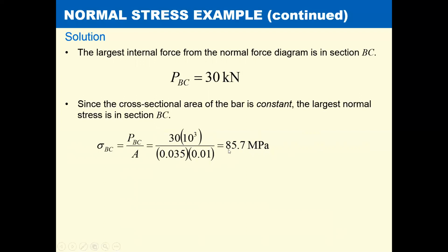And so we don't want to write out an answer with a whole lot more significant digits. In fact, maybe even 3 significant digits here might be stretching it a little bit. Maybe it's a little more appropriate to use 2 significant digits. And in that particular case, obviously the answer would be 86 megapascal. But this would be the answer if the solution is required to be to 3 significant digits.